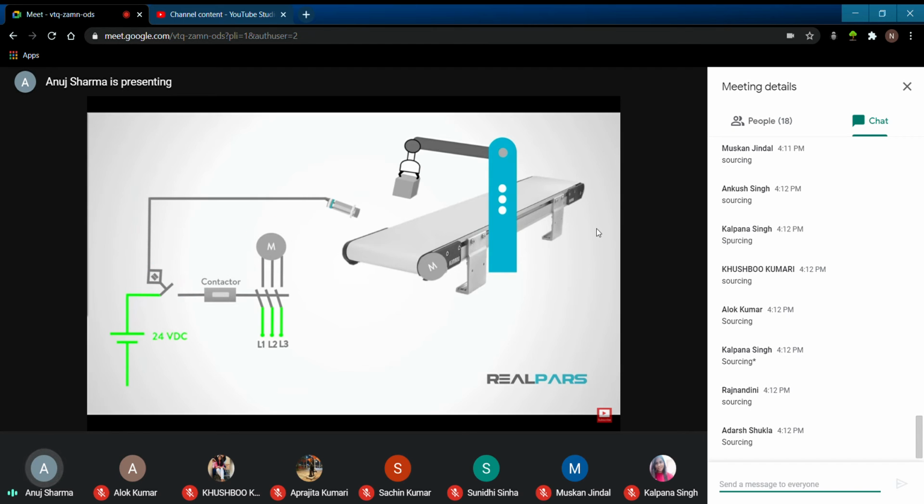DC power supplies are referred to by their voltage and capacity, indicated by how many amperes they can supply. The more amperes a power supply can deliver, the larger and more expensive they generally are. In DC PLC circuits, the power supply almost always supplies 24 volts DC to the connected devices. In this diagram, a DC circuit is shown, which turns on a motor when a proximity switch senses the presence of a part or an object in a specific location.